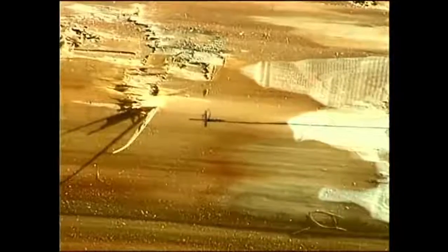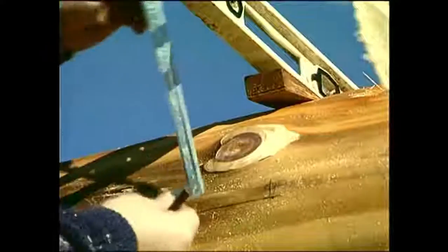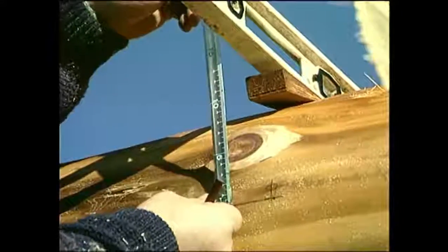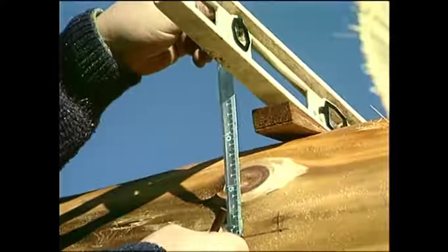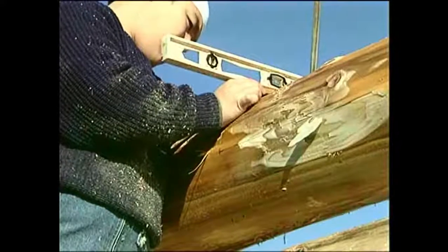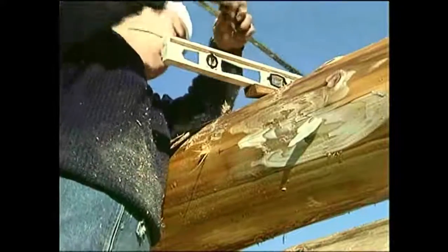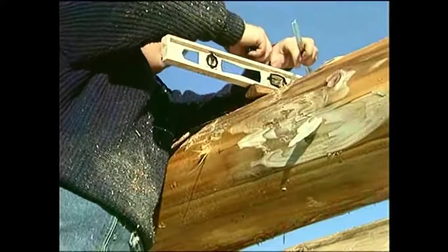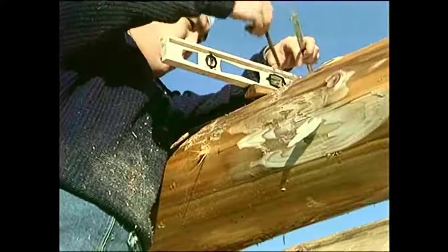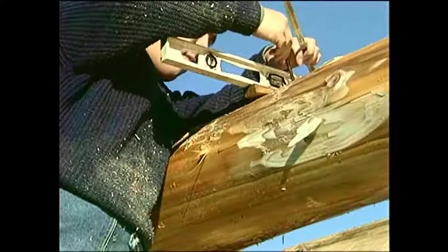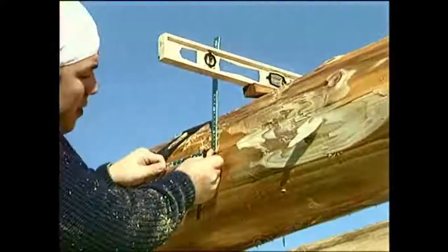On the other side of the log, you can again measure from the foundation line, or better, you can use a level across the top of the log to locate your height line on the other side. Steady the level with a wedge, then get an accurate distance to the header line. Mark the position of the level so it can be repositioned for the other side.